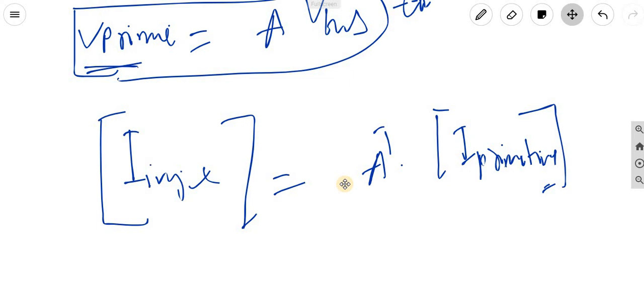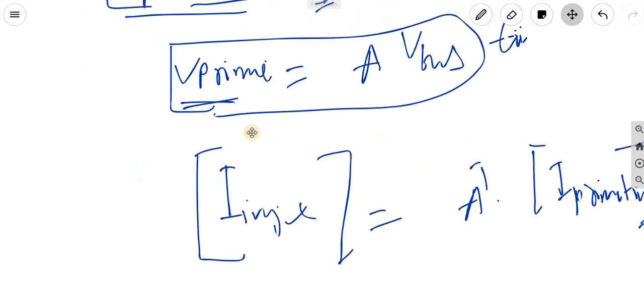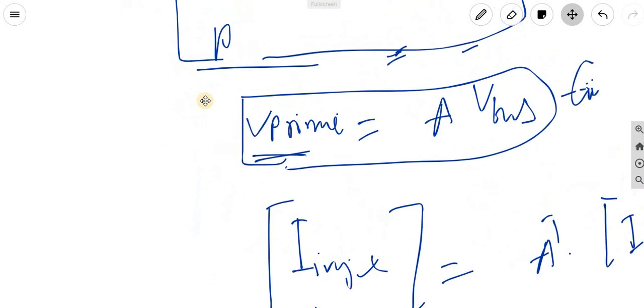And beforehand, firstly we have to do the naming of the branches A, B, C, D, E, whatever the number of branches available. So you name it firstly. In that sequence you have to do. Otherwise you will not get the proper elements. Okay. And with this, using the singular transformation way you will get the result. Okay. You just compare with the previous one, what you have done using the direct inspection method. Okay.